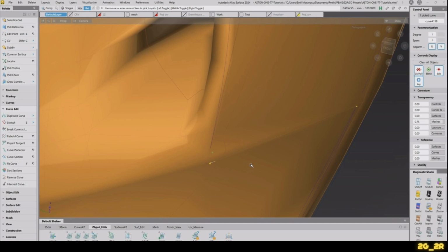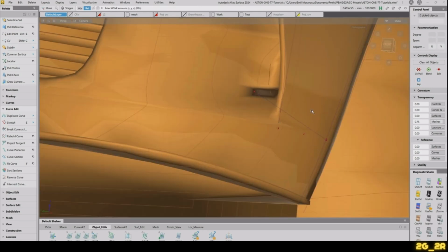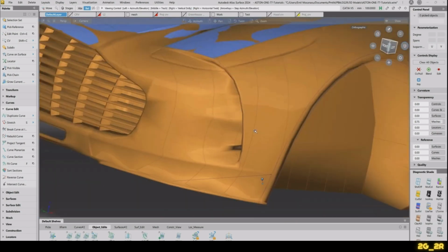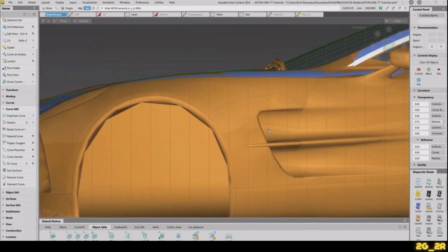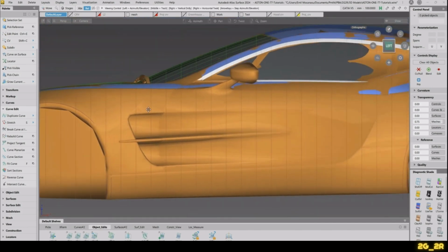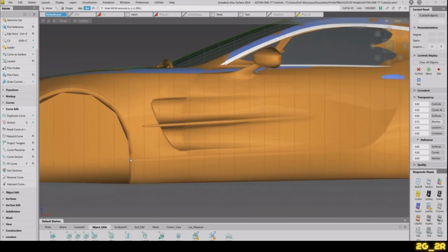This one, instead of being a dead straight curve, we'll turn it into degree 2. Snap the point there. This one moves a little bit out. And then when we've surfaced this, we will fine tune those. So that one is done. Now, as I said, we'll try to bring in here one curve. And we see here, we would need one curve here.